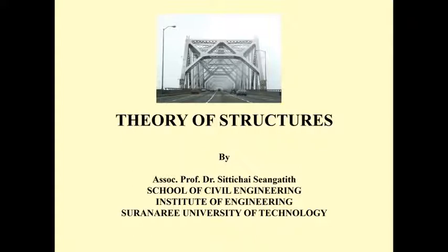Then we use the method of joints to cut each joint of the truss to determine the forces in the truss members. And we also have the method of sections, when we cut a section of the truss, and we use the equations of equilibrium to determine the forces in the truss members.